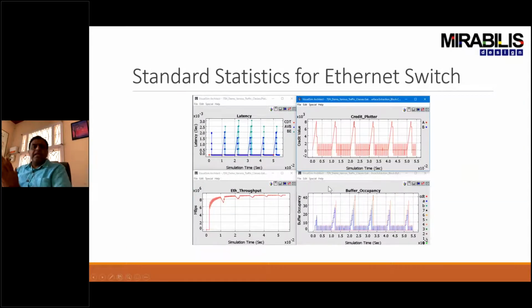Now, a completely different set of statistics. For example, here you can see the latencies. One of the things you notice here is the red is always here, which is very important because the control data times should not have an alteration. They should happen exactly at the slots. Those are happening. But these spikes here are related to the credit policies for A and B. In this case, they're only sending out A traffic. So you can see what's happening. These are all the good times, and these are where it's consuming a whole lot of credit, and it goes into negative mode.